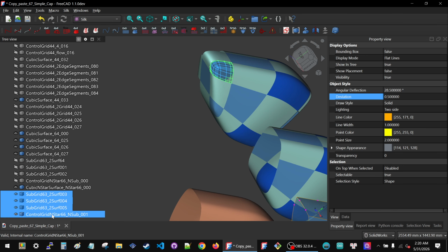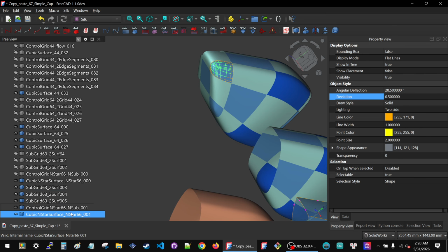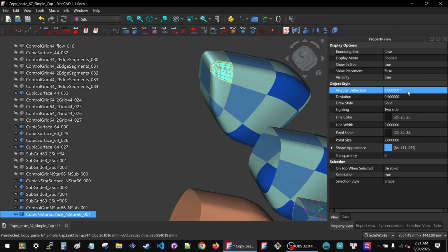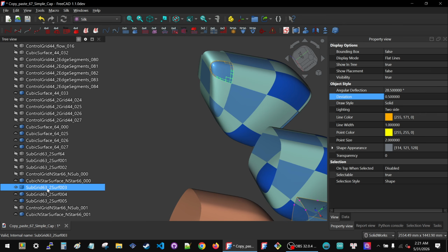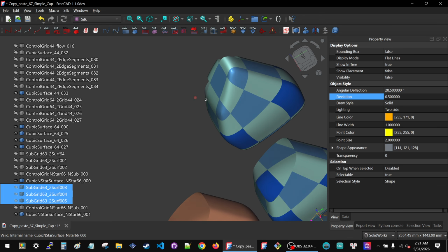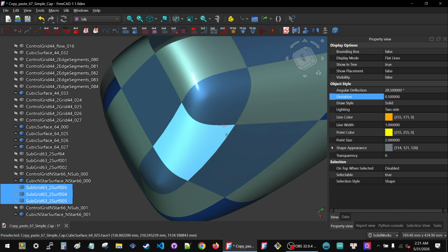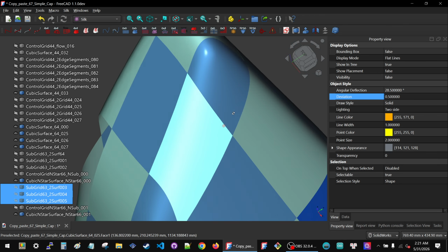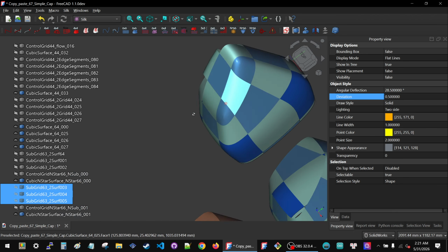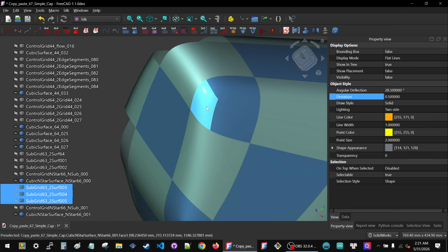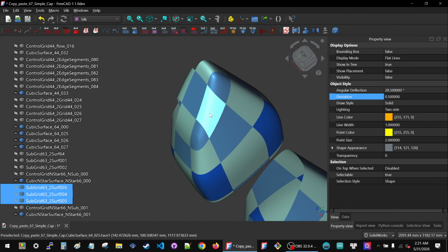Full subgrid, surface, select the surface, 1 degree, 0.3, hide the subgrid. Hide the grid, hide the subgrid, and see, okay, this one has a much less visible defect immediately than this one did, because this corner here is almost flat.